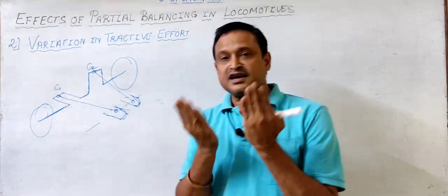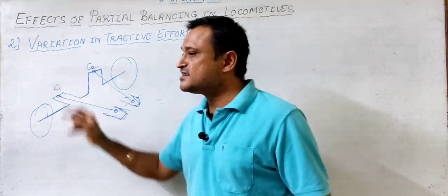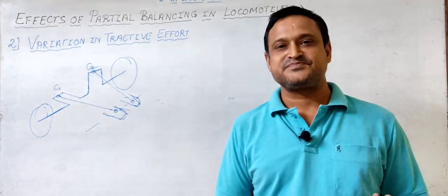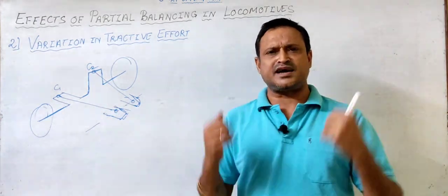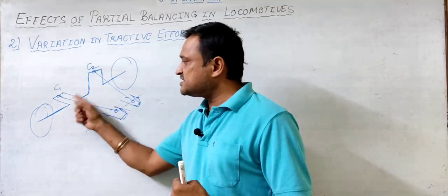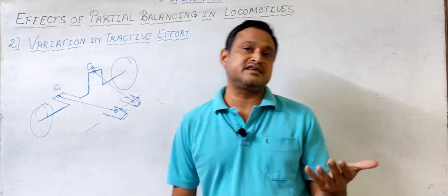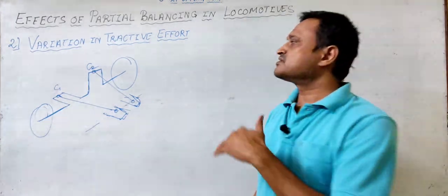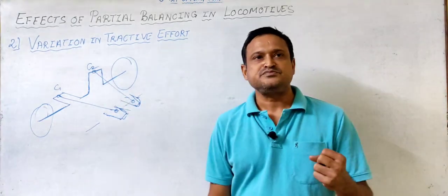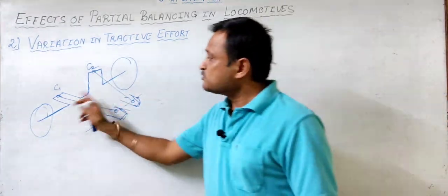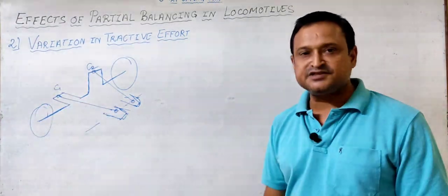If both are at the same phase, then for both cylinders the transmission angle will be 0, right? In that case the required torque to overcome the inertia will be too high. So that is why this phase is maintained, so that if the transmission angle is 0 for one cylinder, then for the other it is a non-zero value. So it will be in a position to provide the required torque to overcome the situation of the other cylinder. That is why this phase is maintained.